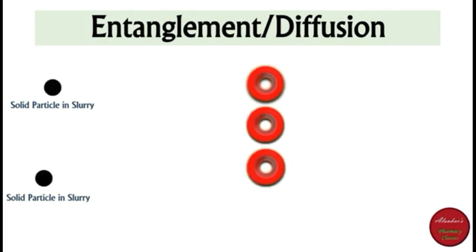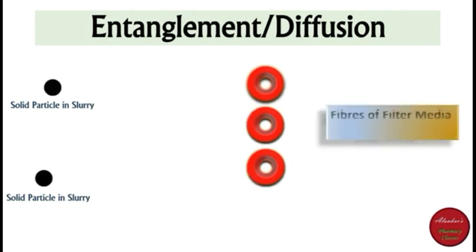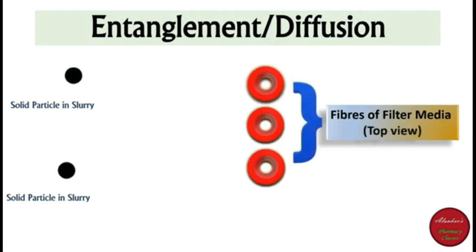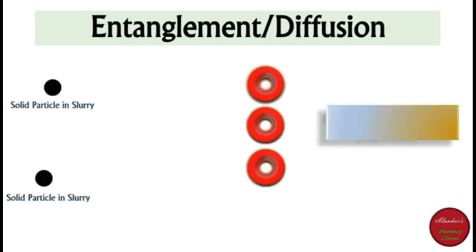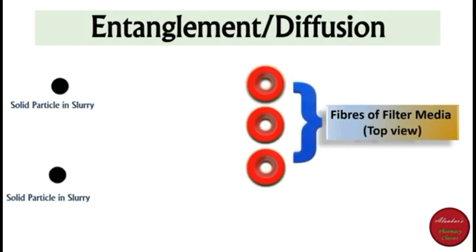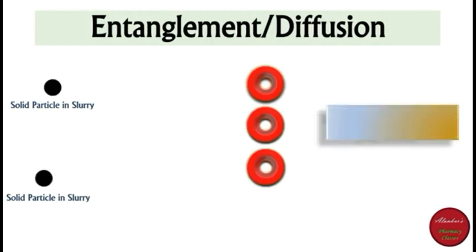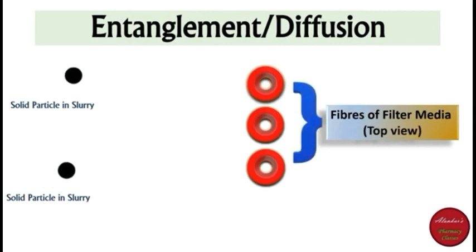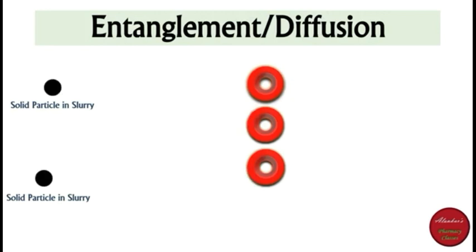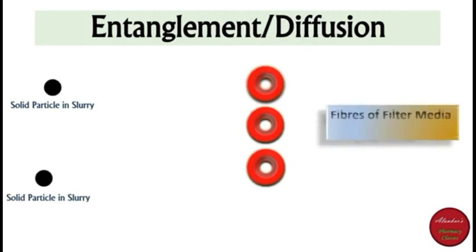Now centrifugation. So in that, first we see the definition of centrifugation. Centrifugation is a unit operation employed for separating the constituents present in a dispersion with the aid of centrifugal force. Then next we see the classification of centrifuge. The first type is the sedimentation centrifuge, and the use of the sedimentation centrifuge is that it is used for blood plasma separation, preparation of bacterial enzymes, manufacturing of insulin. It is also used for clarification of olive and fish liver oil.